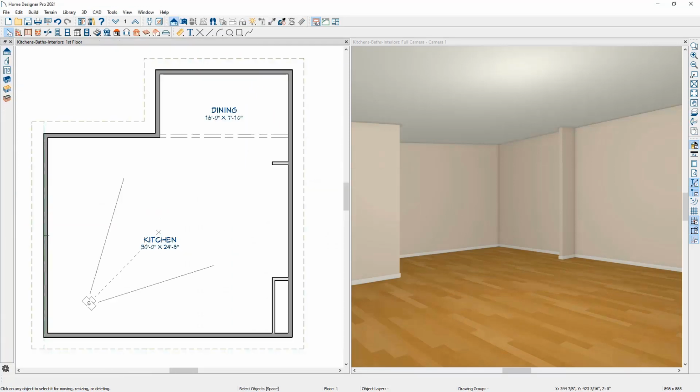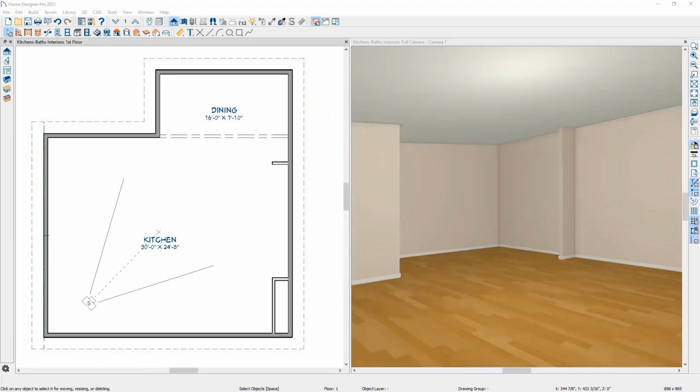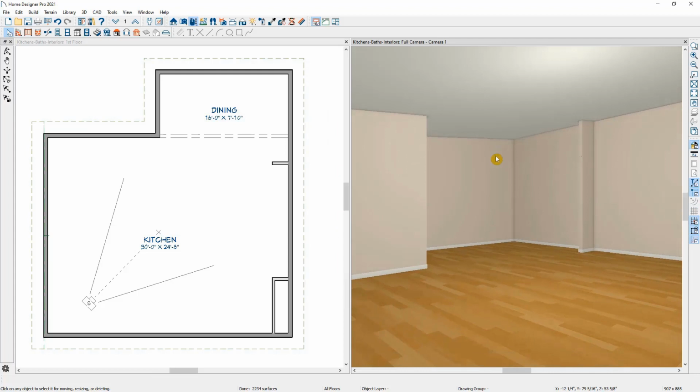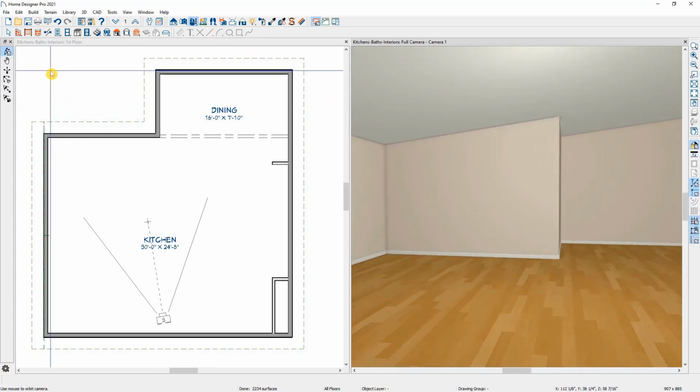And next I'm going to add the beams that you see going across our ceiling here. And to add these beams, we're actually going to use the Soffit tool in the software. I'm going to reposition my 3D view just slightly for now. So to use your Soffit tool, go up to your cabinet options, and you'll notice that there's an option here for base, wall, full height, Soffit, and then a few other options we'll come back to.